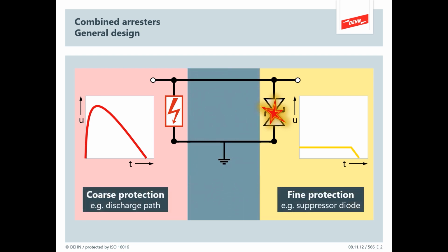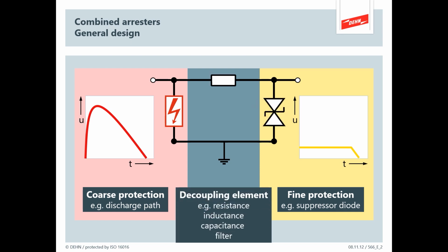So that's when we have to have some coordination, and this is true of any SPD circuit. This decoupling or coordinating component will introduce resistance, inductance, or capacitance, so that when the type 1 operates, that gives me coordination with the more sensitive components further in the SPD housing, so they act as a coordinated circuit.